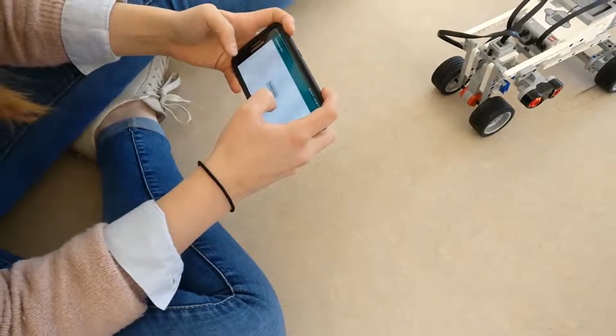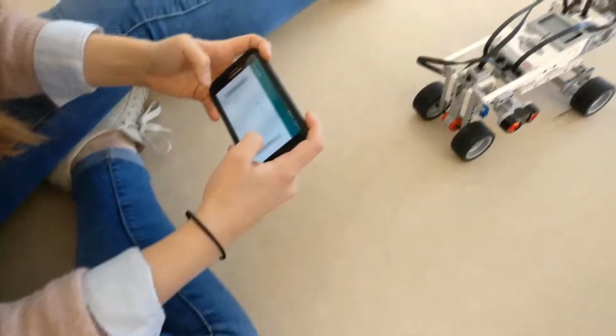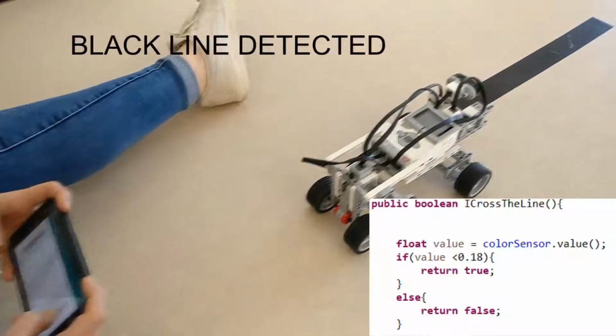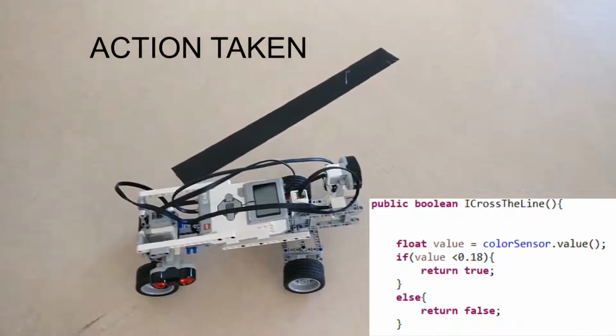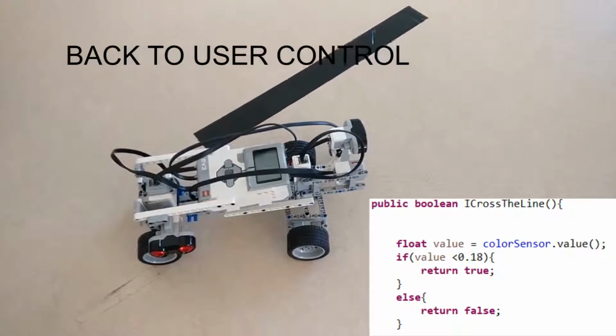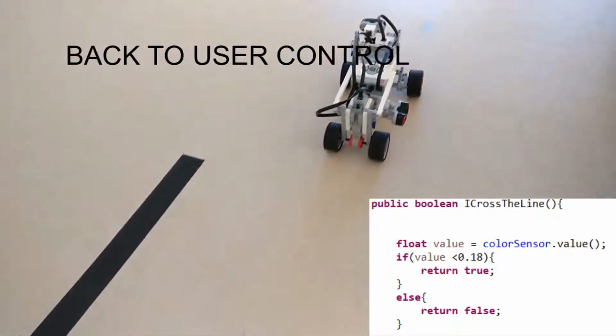Let's now take a look at lane assist. As shown in the video, the car will detect a black marked line using the color sensor. If the sensor value reaches a certain threshold, it will detect it as a color black, and it will take the necessary action. The car will autonomously turn and return the wheel to the original position, so the user can take control again.